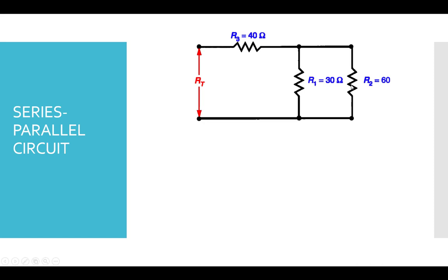How do we combine these? Well, it depends on how they're connected. Are they connected in series? No, because they're connected at 2 points. Current doesn't flow into one and directly into the other. So that means that these are in parallel because of these branch points.